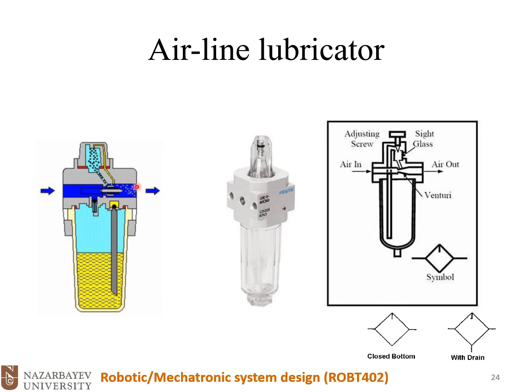So now you see that we have droplets of the oil inside the airflow. These droplets of the oil will reach our moving parts by the air, and we could lubricate our cylinders or directional valves, and it's essential to any pneumatic systems.